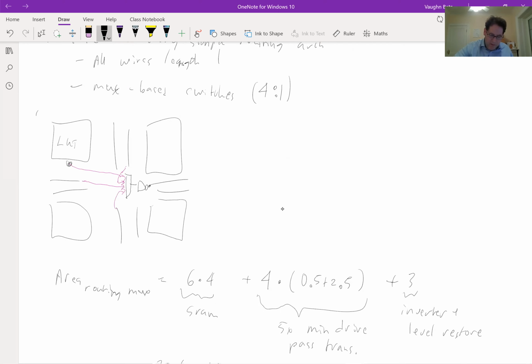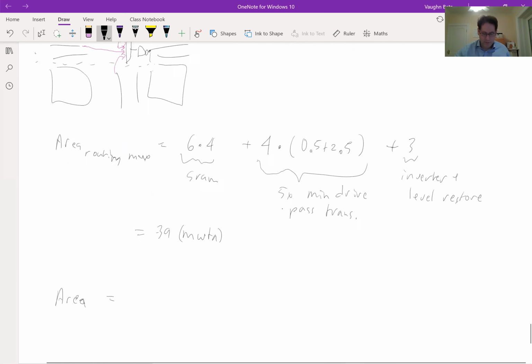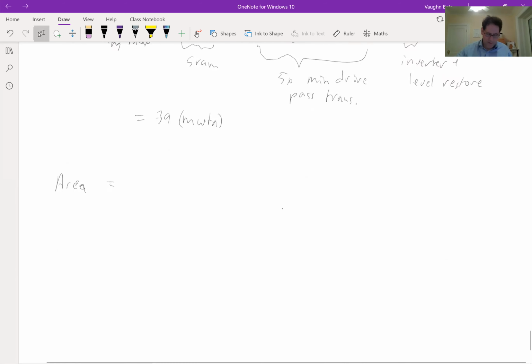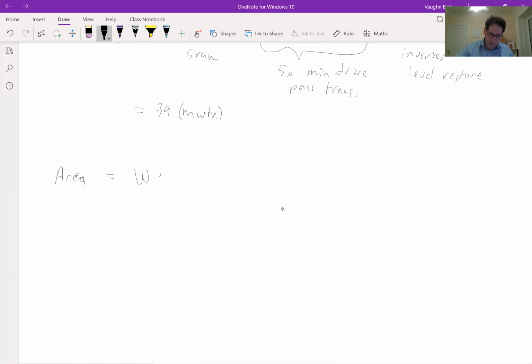So again, my basic unit that I'm repeating is a logic block plus 1 piece of a vertical channel, 1 piece of a horizontal channel. So I'm going to need 12 of these routing drivers for the vertical wires and 12 for the horizontal. And that's my replicated unit. Okay, so I need W routing drivers times 2 different channels times the area I just computed.